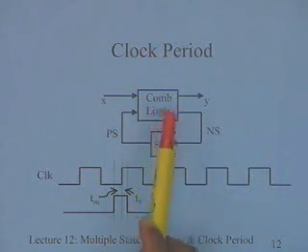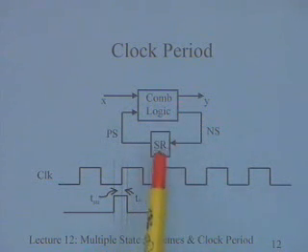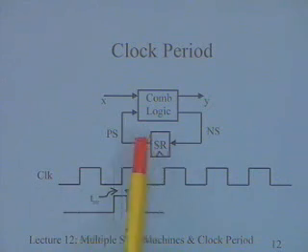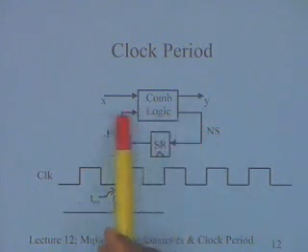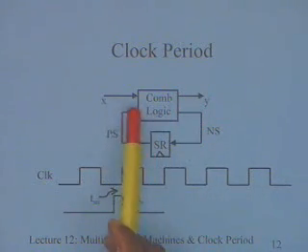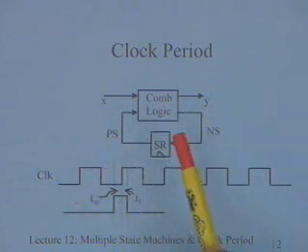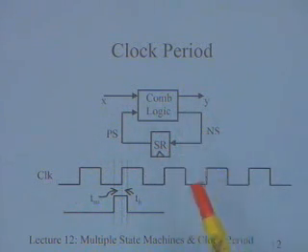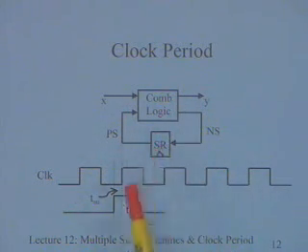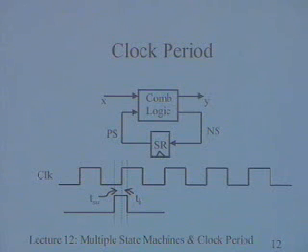So I have the delays that are associated with the combinational logic, and we will talk about those delays. I have some delays associated with the flip-flop. Apart from the basic delays, which are the propagation delays, the delays after which, when the input changes, outputs take some time to stabilize, the flip-flop also has two more timing specifications which are associated with the input.